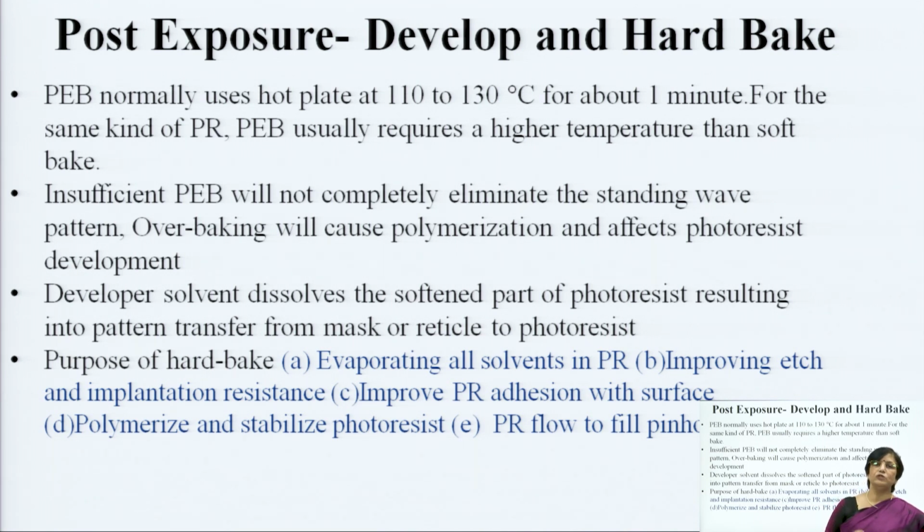Now, after exposure, you have one more method in the latest technology, or in recent days: you carry out post bake, also called post development bake. What is its purpose? You use a hot plate at 110 to 130 degrees for 1 minute. It is for a very small duration, and the post bake is at a higher temperature than the soft bake process, but it is basically to ensure that whatever exposure has happened, that exposure many times creates problems in the area.